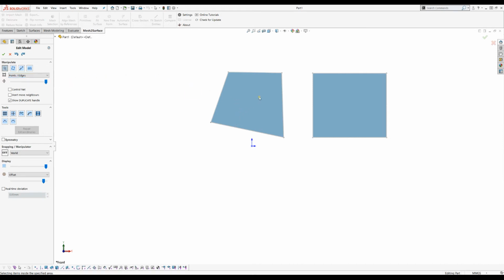What it means is that you cannot select any face, but you can just move and highlight an edge, and if you want to select it, you just click on this edge. It becomes yellow. You can also select a point, or you can use the rectangular selection. Now, if I want to add more to my selection, I can just hold the Control key and it will add to the existing selection. If I want to unselect something and leave the remaining, I will just hold the Shift key and paint with the rectangular selection over this area that I don't need to be selected.